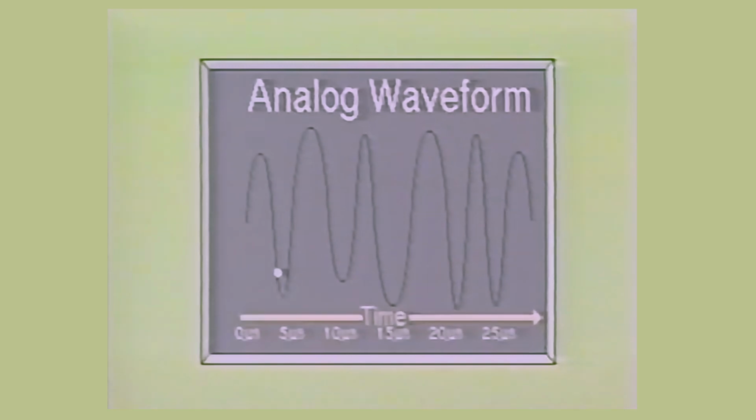For example, one of the limits might be in the unit of time where 0 is the turn-on point, and all units to the right of 0 would indicate a specific period of time. Another limit could be in the magnitude, used to indicate the values of current or voltage. In certain situations, the low-end limit could be 0 volts, with all units above the low-end limit indicating voltages higher than 0 volts. As you can see, the analog signal may have any value within this limit range.